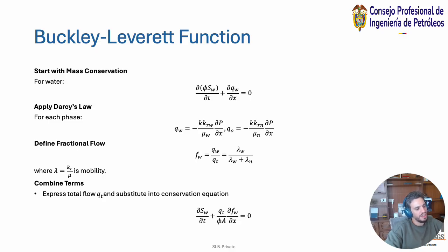And it's again derived, like most things in physics, on either the conservation of mass or the conservation of energy. But here they're using the conservation of mass equation, and they're just putting it in the form of a Darcy's law equation, a multi-phase flow of Darcy's equations, which helps you optimize the recovery strategies in oil reservoirs. So that covers the Buckley-Leverett function.